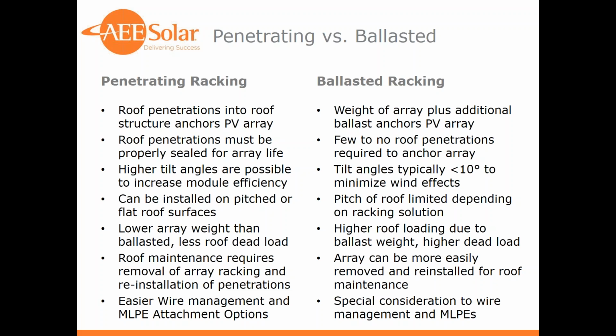Penetrating racking, because of the use of rails and other wire management, often makes wire management and MLPE attaching easier. We have to have special considerations if we're using ballasted racking for our wire management to keep the wires off the roof. And the MLPEs, any optimizers, microinverters, or shutdown devices, have to be attached using frame mount solar attachment kits.